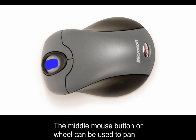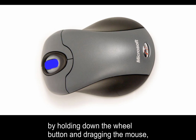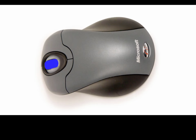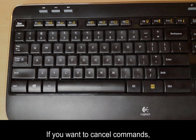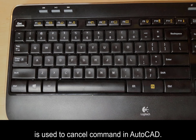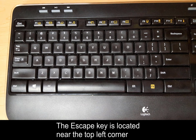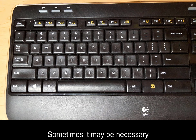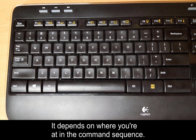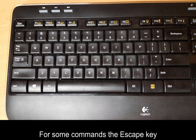The middle mouse button or wheel can be used to pan by holding down the wheel button and dragging the mouse, or to zoom by rotating the wheel in real time. If you want to cancel commands, the Escape key on the keyboard is used to cancel a command in AutoCAD. The Escape key is located near the top left corner of the keyboard. Sometimes it may be necessary to press the Escape key twice to cancel a command. It depends on where you're at in the command sequence. For some commands, the Escape key is used to exit the command.